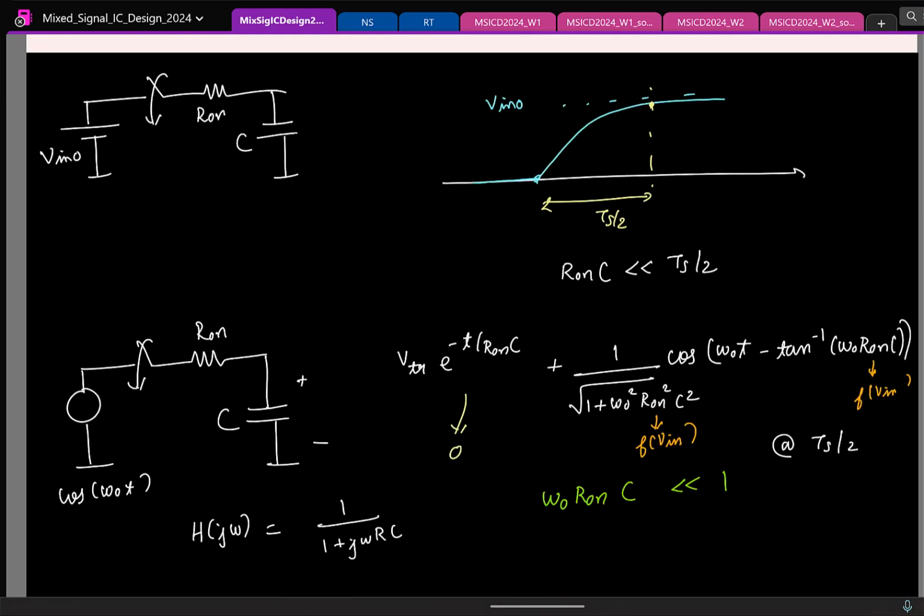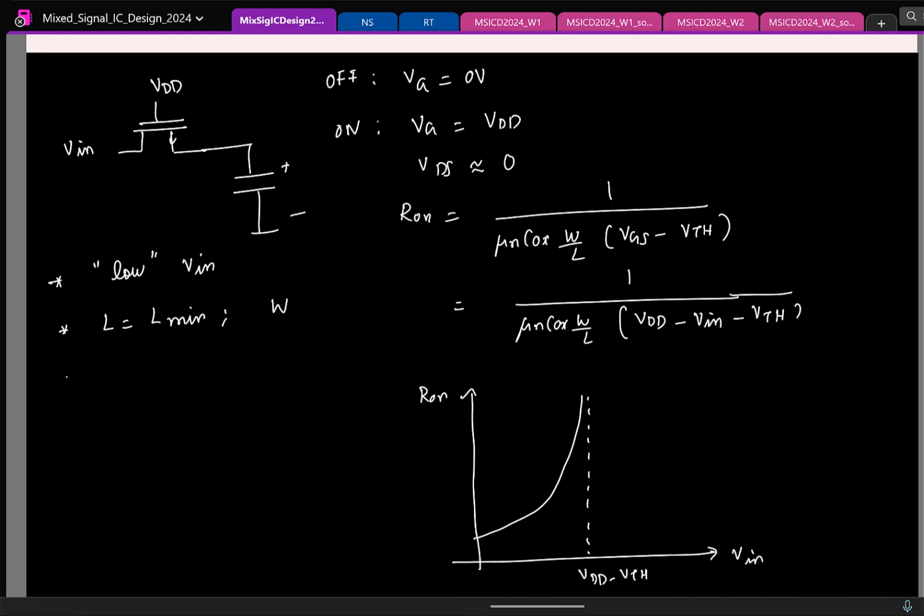So if you want to reduce this effect of nonlinearity, from this expression, what is the only control you have? Let's say it's fixed by something else, but what is the choice you can make? Yeah, the point is you keep this factor smaller, because nonlinearity is arising basically because of these two factors. The smaller you keep omega RC with respect to 1, the smaller will be the nonlinearity. That's what you are indirectly saying, right? So again, that brings up the second thing. So let me mark it here.